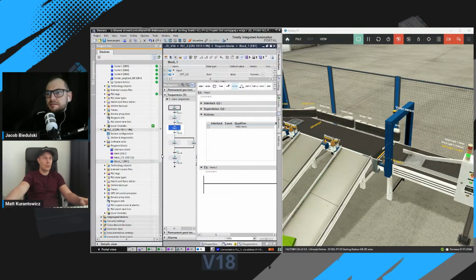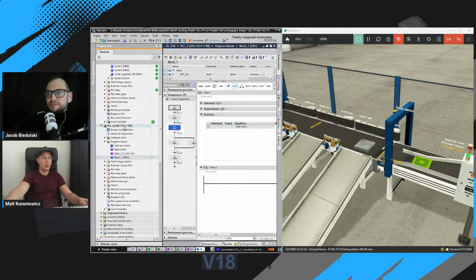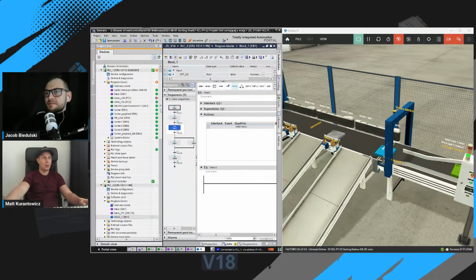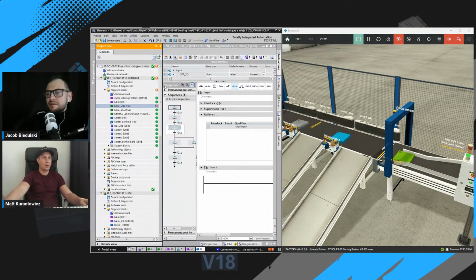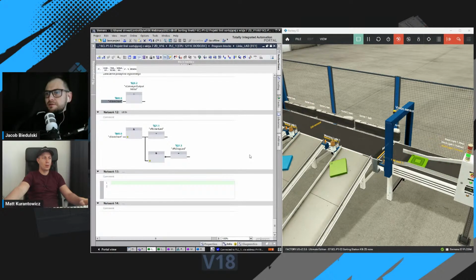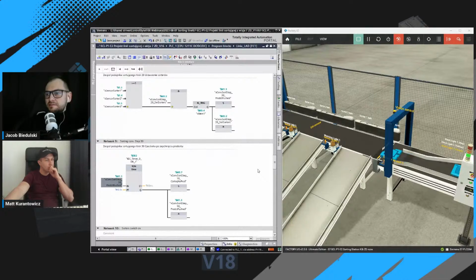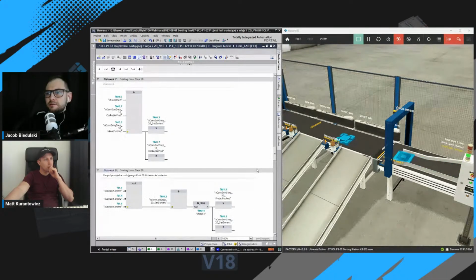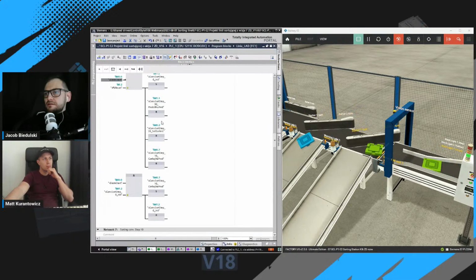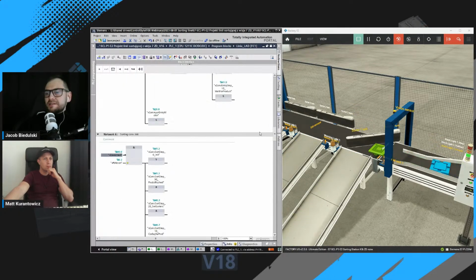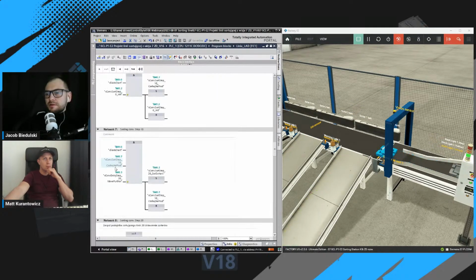SFC is possible only for the top-end PLCs from Siemens, the S7-1500. So if you code in ladder logic or in SCL, you can also code a sequence, but as we do in this case, we just use a sequence based on our coding method.